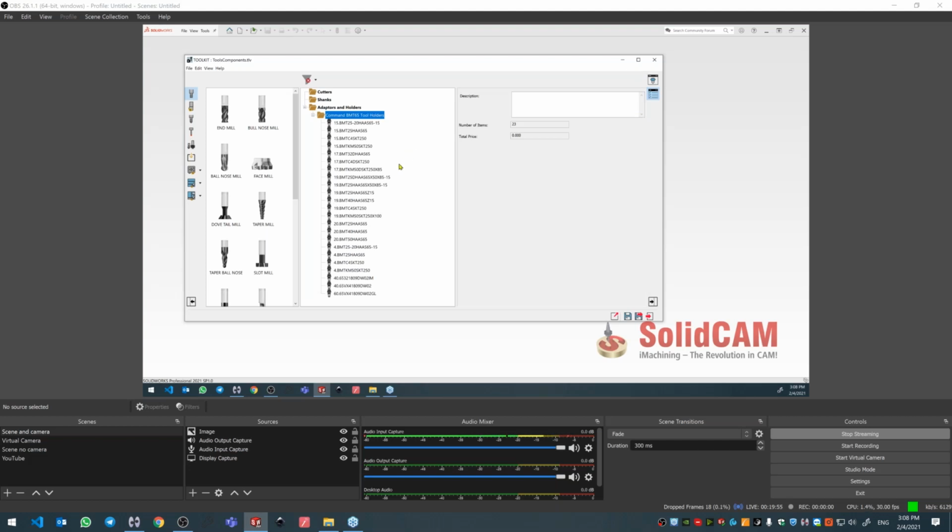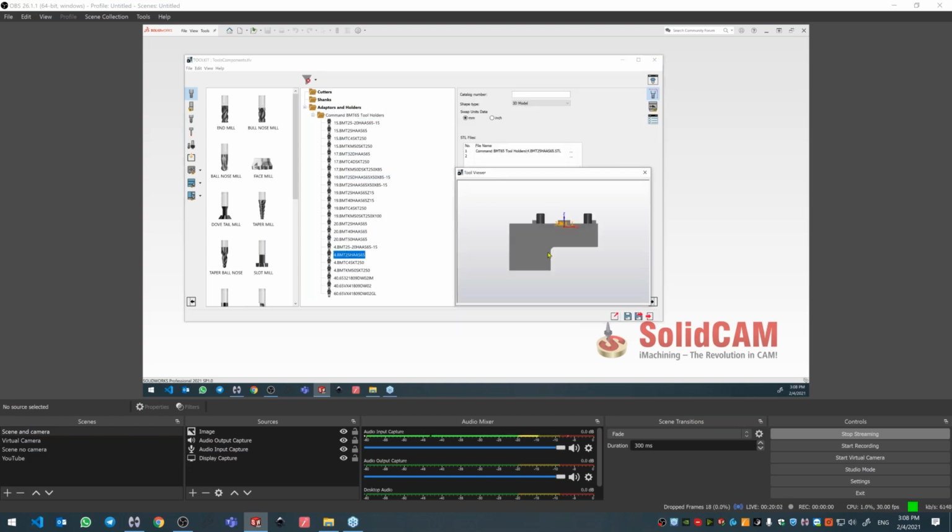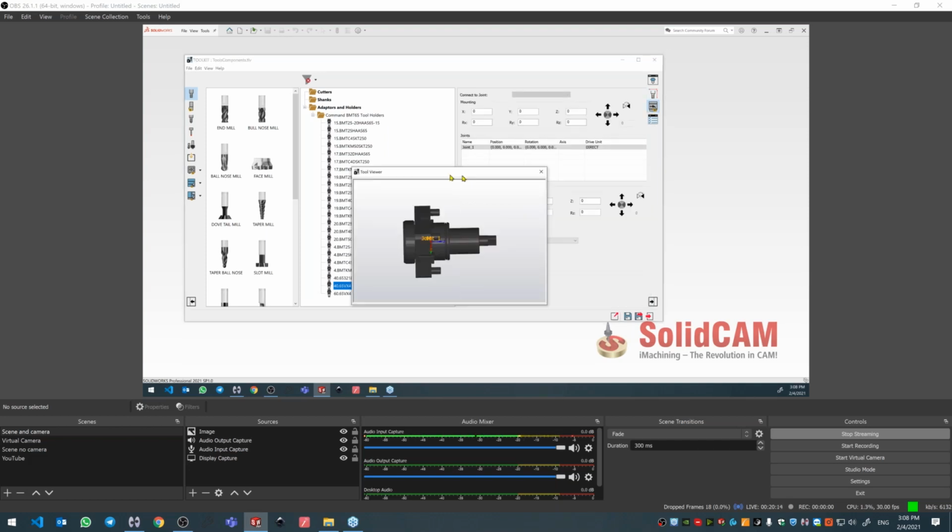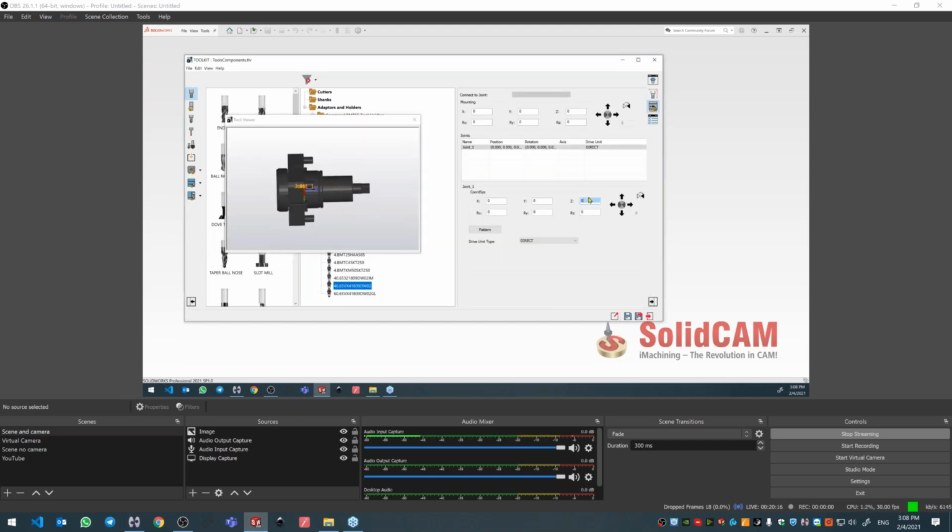What I need to do now is to edit the holders. So I can open the tool picture view, and go to each holder and define where is my mounting point for the station on the tool on the turret, and also the connection. We call it joints.